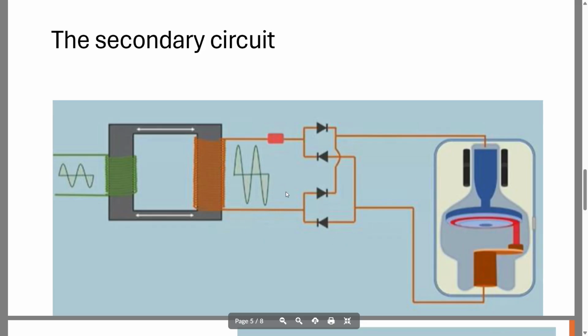The whole purpose of this process, again, we're trying to convert AC to DC, alternating current to direct current. So this sine curve is showing alternating current because we have fluctuations both in the positive direction and in the negative direction. But using our diodes, you can see that we're only flowing from negative to positive, from cathode to anode. If there were alternating current past this point, we would see flow in the opposite direction as well, from anode to cathode, and we don't want that happening. So really, rectification is this process where these negative sides of this alternating curve are flipped. So we have just curves going in this direction.